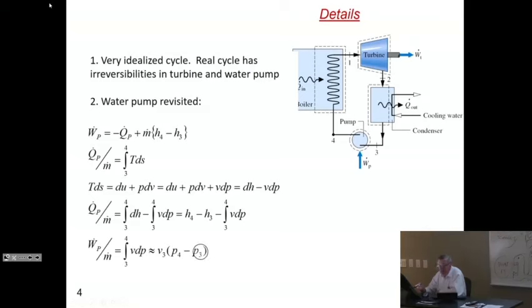So there is a correction to pressure, and that is the work that you're going to have. Note that this is the inverse of what we have generally. Generally, you have the work that is PdV, not VdP. But here, this is the enthalpy change, this is the heat, so then this has to be the work. The work is a specific volume times a change in pressure.